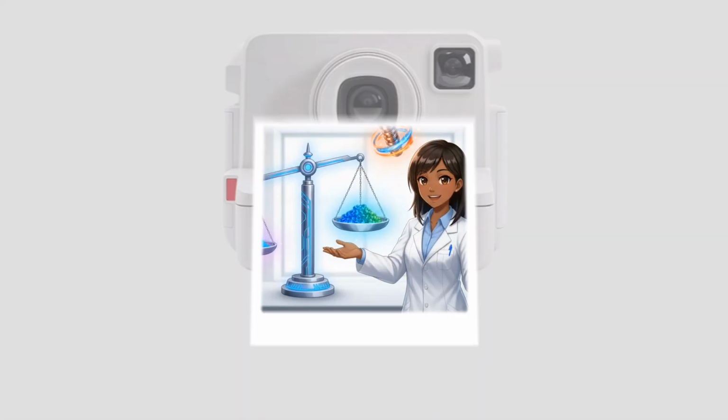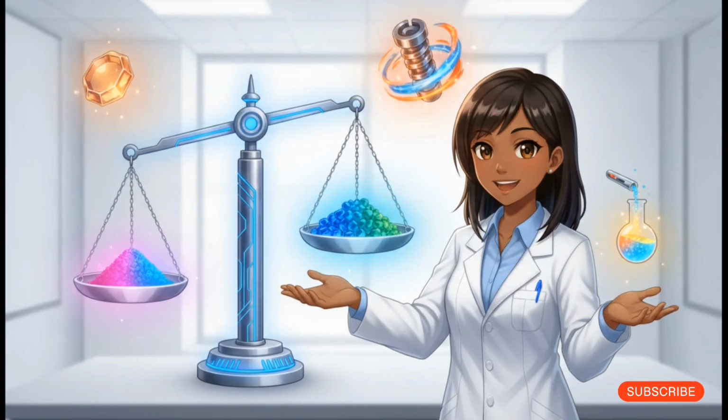So what do you do if your filter pressure test shows terrible results? You don't just scrap the batch. You run through these 5 actionable techniques. You can pick a better carrier resin, tweak to the correct screw design to adjust your shear, optimize that processing temp, or throw in some dispersing additives. But I really want you to pay attention to number 5,